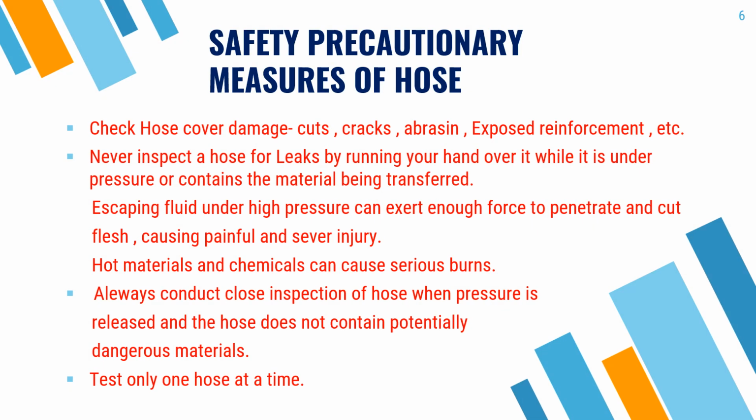What are the safety precautionary measures of the hose? Whenever we are using the hose at our work area, what are the safety points we should know? Those are the following. Number one is check hose cover for damage, cuts, cracks, abrasion, exposed reinforcement, etc.